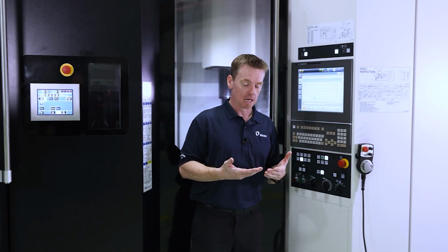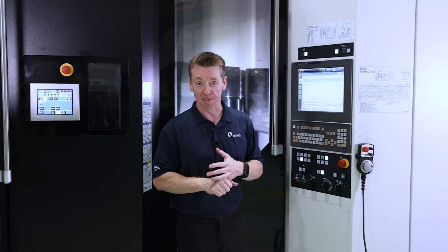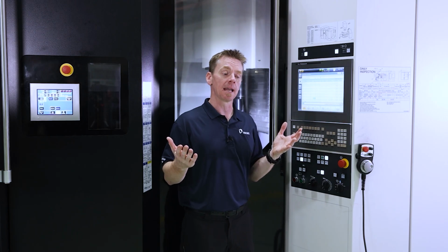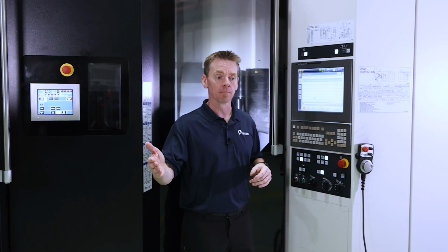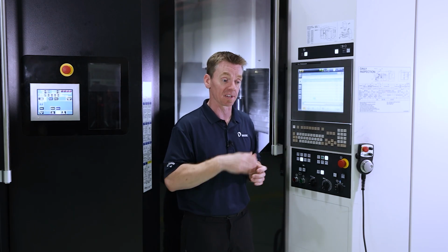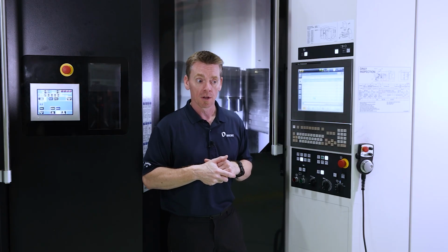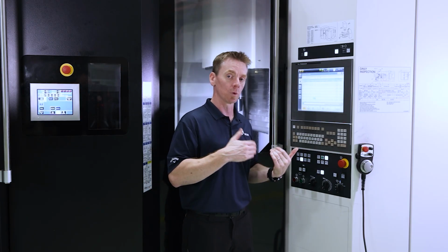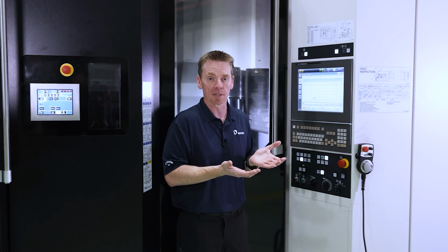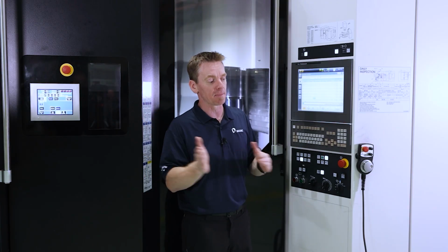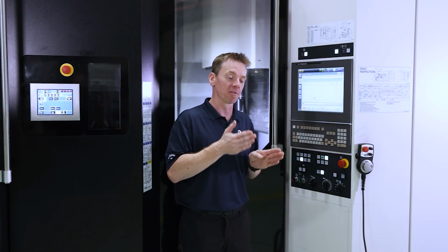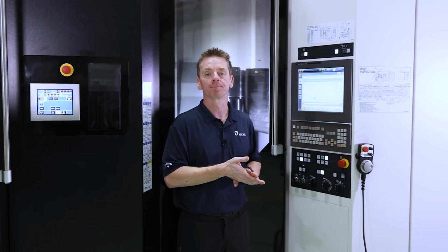What else does this give us? If you program a lot of jobs using a CAM system such as Mastercam, you can create master tool libraries. Now you can go from 1000 to 9999. You could even break it down so that anything in the 1000s are end mills, anything in the 2000s are drills, and anything in the 3000s are corner rounding end mills. So you can give some identification to tool numbers and the tools being put in the machine, so people know what they should be putting in case there's a massive discrepancy. It allows you to carry a master library and use it to program across all your jobs because you're separating the information. Every tool has a unique tool number.